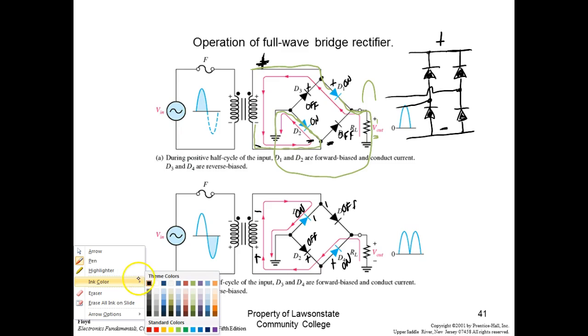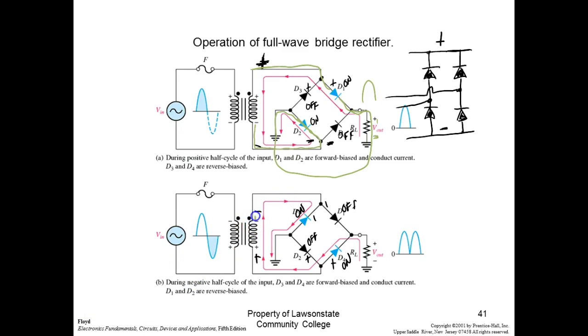Now my current is coming out of the other side of the transformer, negative to positive. Okay, it's going to go down through this one. It's on. It's going to go out through circuit common, come up here. Still coming negative to positive, right? Going to come back, looking for the positive, going to go back that way. So these guys are swapping every alternation. So what we get out is this. Of course, here we don't have to deal with the center tap.